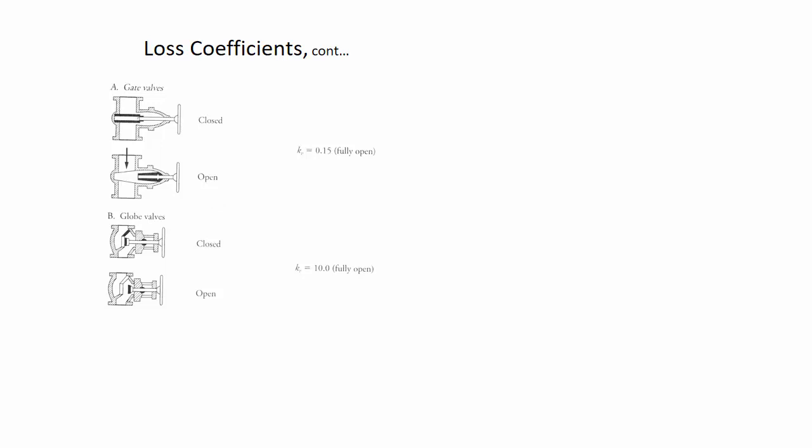Good question. Yeah, that's a good question, like the operational considerations. As far as the operational considerations, I'll mention that if you have a high pressure environment, a globe valve is going to be better to prevent leakage than a gate valve is. And that's because there can be a rubber O-ring that goes around the opening here, and this globe can go down and kind of seal against it with quite a lot of force, and it's harder to have that same seal with a gate valve.